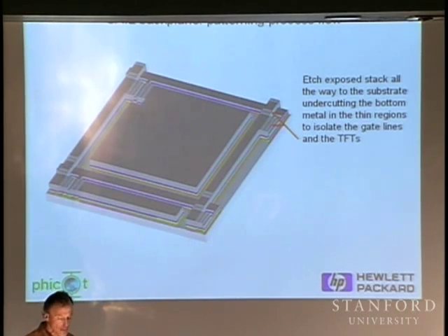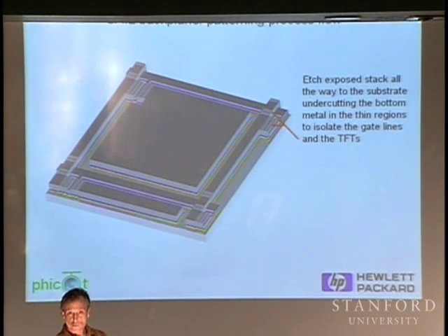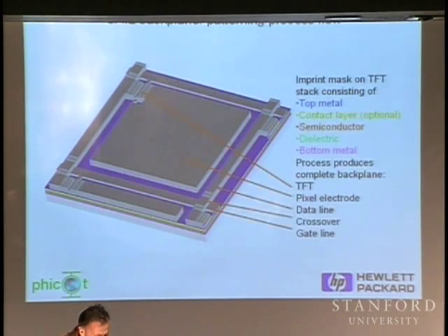This was something we were originally really worried about: could we control this process well enough? Because I need to etch just the next step in that mask. I want to remove it, but I don't want to remove the one above that. So my uniformity has to be such that I still have enough margin to have it serve as a mask once I've removed that next 0.7 of a micron.